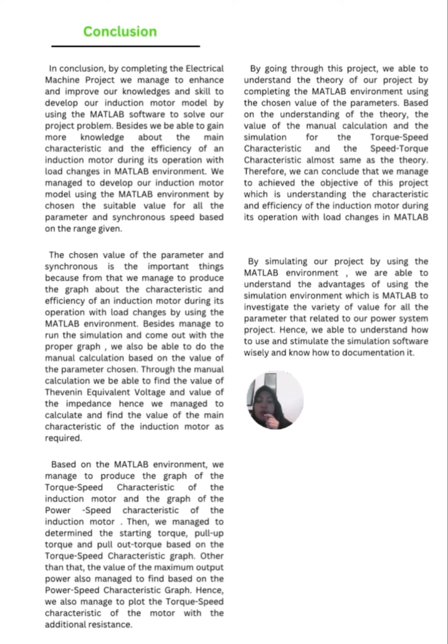Based on the MATLAB environment, we managed to produce the graph of the torque speed characteristic of the induction motor and the graph of the power speed characteristic of the induction motor. Then we were also able to determine the starting torque, pull up torque, and also breakdown torque based on the torque speed characteristic graph. Other than that, we also managed to find the value of the maximum output power based on the power speed characteristic graph. Hence, we also managed to plot the torque speed characteristic of the motor with the additional resistance.